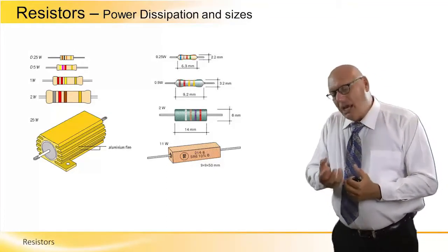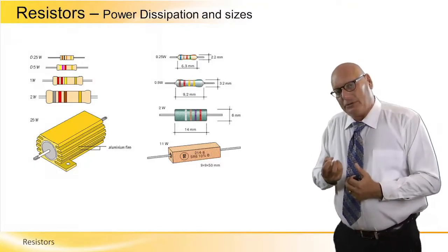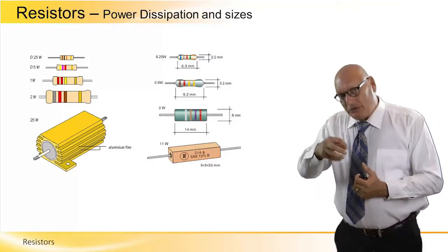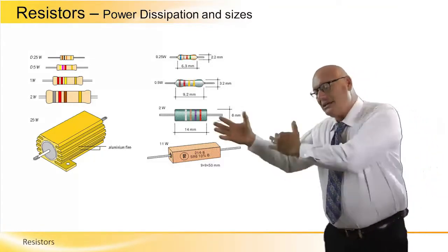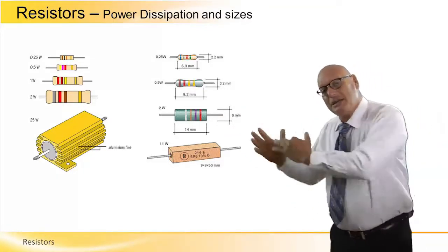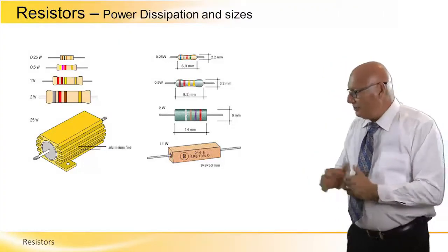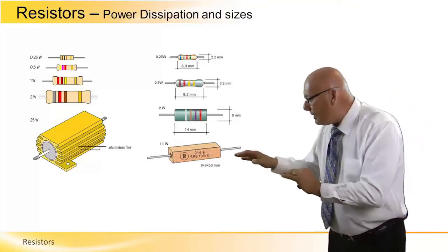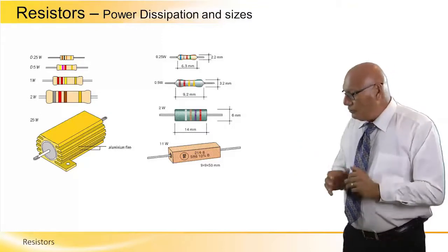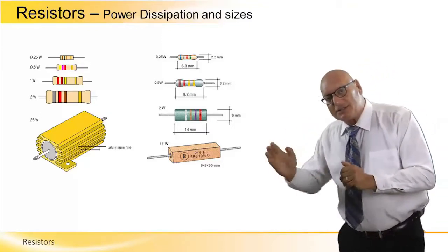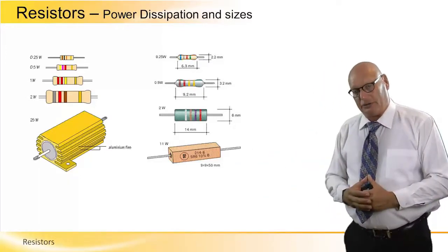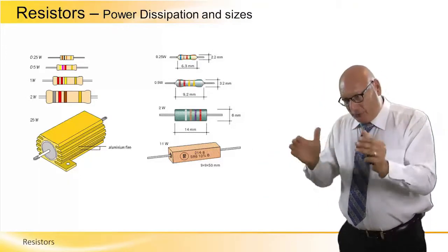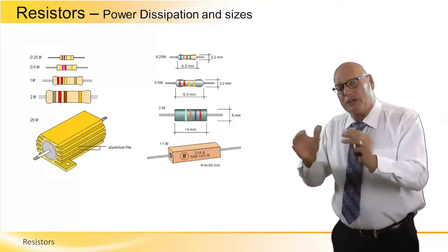It actually takes all the heat which is being generated inside the resistor and sinks it out to the open air. The reason that we have these fins on the aluminum is to increase the surface area and the contact area with the air. It's much bigger than if we used just a smooth aluminum case.